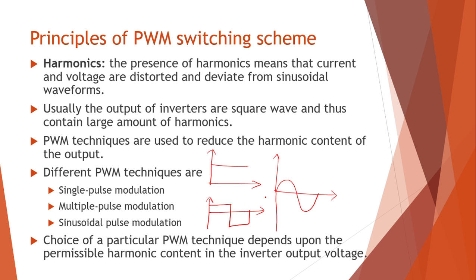And you can see directly by comparison that you just have a positive cycle and a negative cycle, but there is a problem. The shape is not at all sinusoidal. Because of this difference in the shape, harmonics are going to get introduced within your circuit, and this will lead to problems in the operation of your devices. It can cause humming noises or other drawbacks while operating. So it is always desirable that you remove the harmonics.